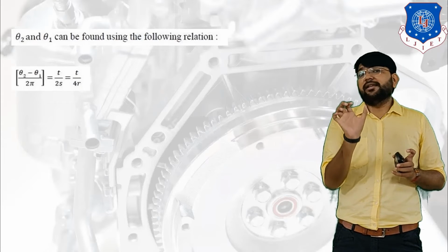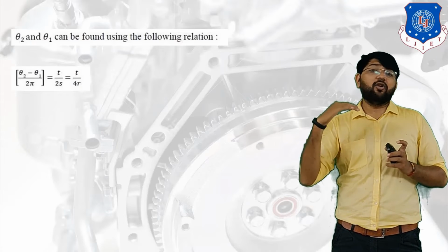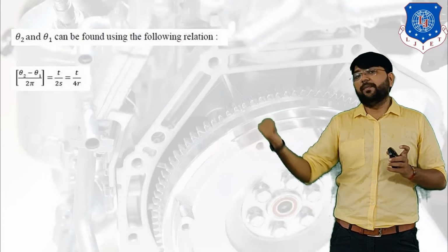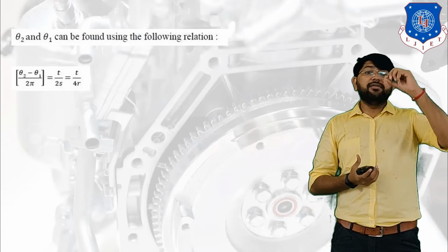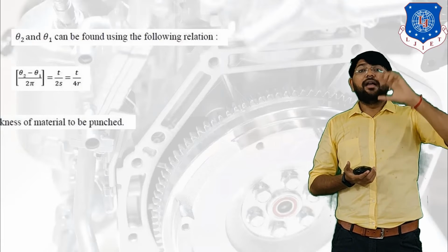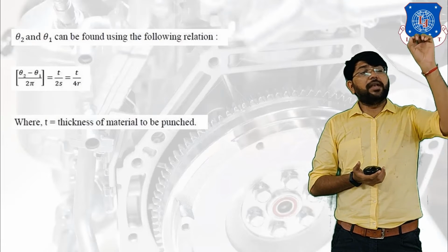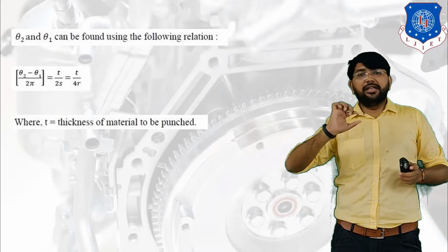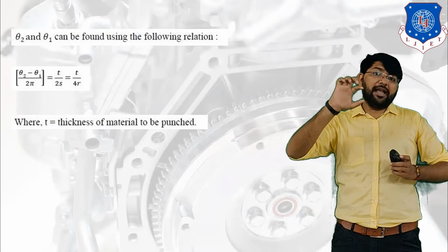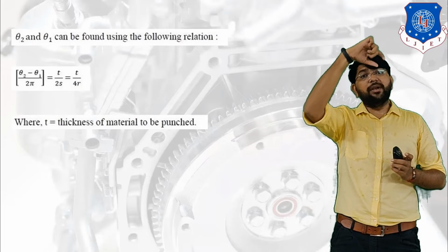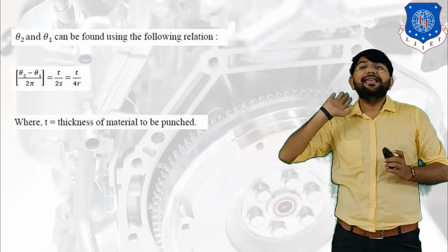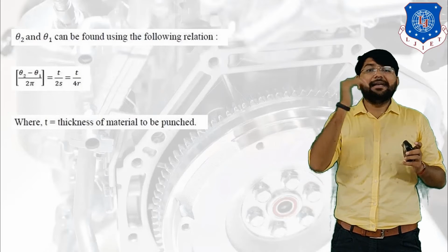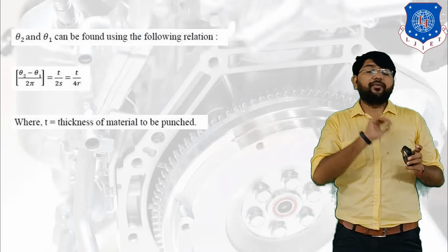Theta 2 minus theta 1 is the same as the thickness of the plate, because the punch moves downward while the crank goes from theta 1 to theta 2, and the punch cuts the plate. So the thickness and the arc between theta 1 and theta 2 will be the same. So instead of theta 2 minus theta 1 you can write T. And instead of 2 pi...